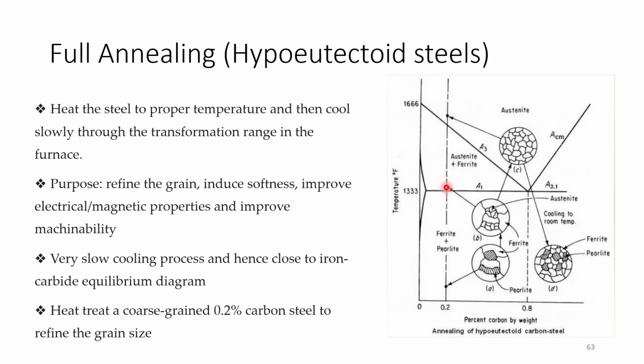When you heat it up to this temperature, the pearlite will convert into austenite, and the ferrite will still be in the form of ferrite. Then the ferrite will start to convert up to this temperature, and keep converting into austenite up to this temperature, then you will have a complete austenitic structure. The higher the temperature that you take it to, the coarser the grain size will be.